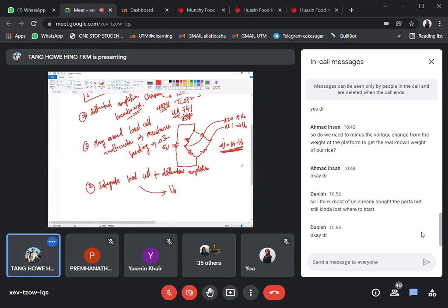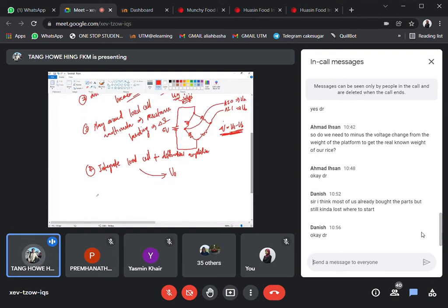Lastly, after you have integrated all these with the differential amplifier, because in step number 3 you can slightly have an idea of how small the value of this voltage is, you may now decide what the amplification gain for this differential amplifier should be.